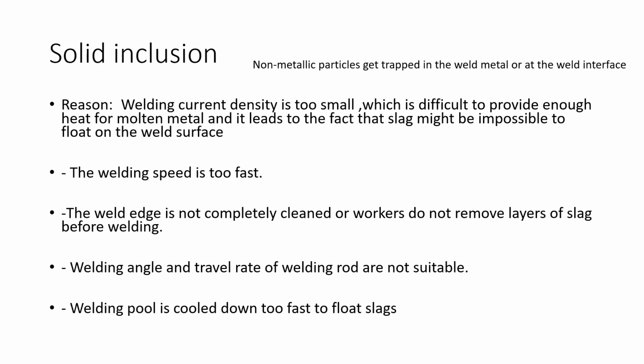Slag inclusion can be prevented if a proper groove is selected and all the slag from the previously deposited bead is removed. If too high or too low welding currents and long arcs are avoided, then this solid inclusion can be avoided.